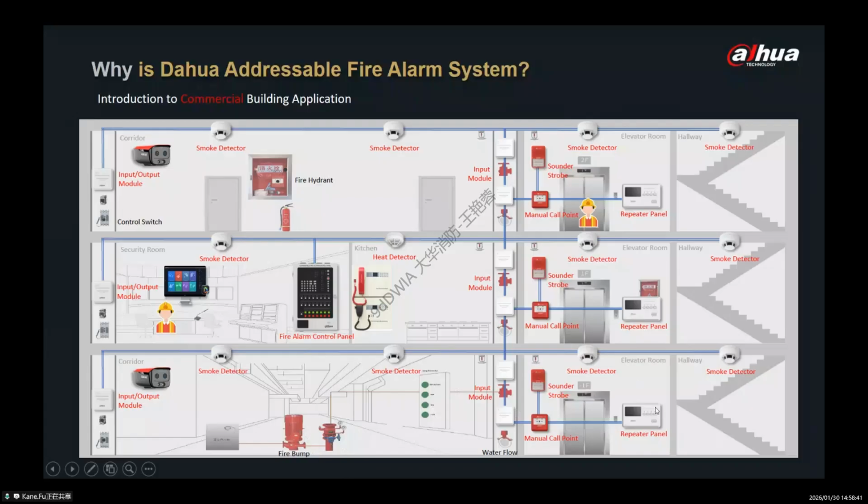For the repeater, we install it close to the elevator entrance and exit to help people quickly check the fire event location. And also the manual call point, to indicate with the alarm device. We can also deploy the flame detection camera here, to make a CCTV and traditional fire alarm mixed solution.